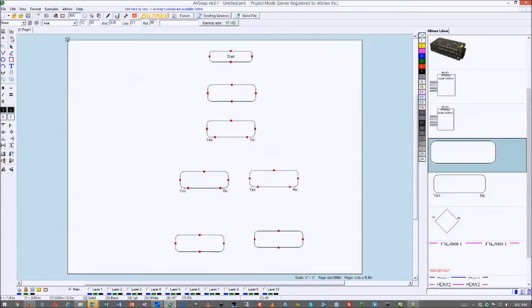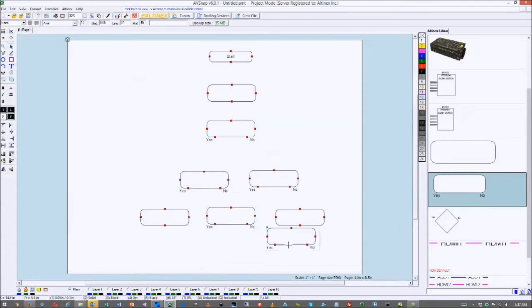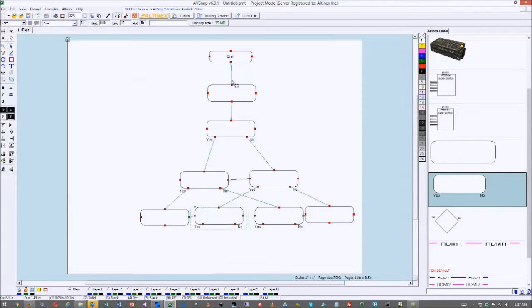Right away, you can turn the flow chart on, and it will automatically connect things together. It doesn't know how to connect it exactly, but it will try to do things as best as it can to connect things together. So let's see if we can fine-tune this connection automatically. Go ahead, turn the flowchart mode on, and you can see that everything gets connected. So far it's good, but you see there's no reason for these to be connected. So just right-click and delete the snap point. Once you delete the snap point, you're done. The same thing here. Delete the snap point for anything that you do not want to be connected.